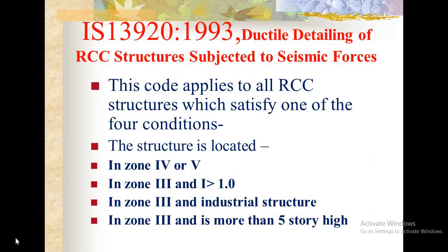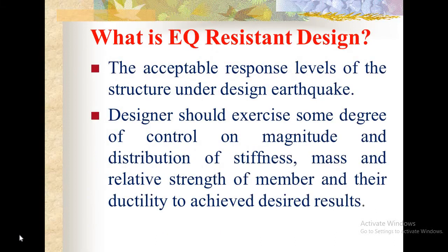Okay, let's see what earthquake resistant design is. It is the acceptable response level of the structure under the design earthquake. The designer should exercise some degree of control on the magnitude and distribution of stiffness, mass and relative strength of members and their ductility to achieve the desired result.